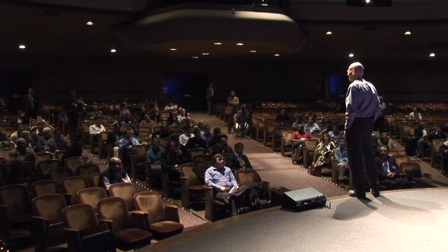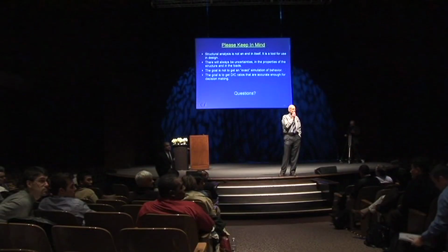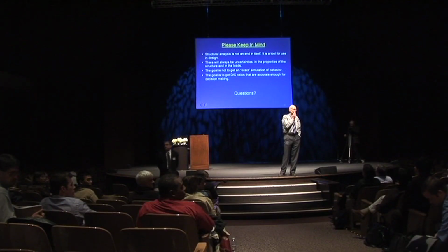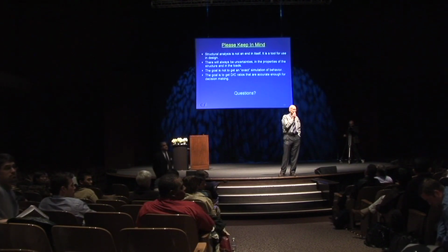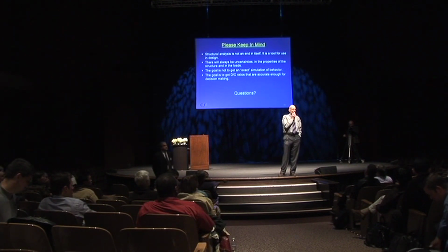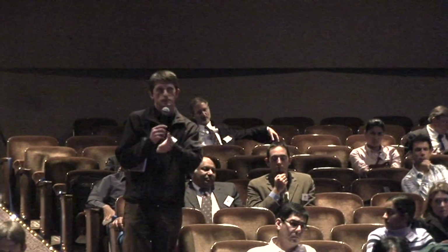Okay, and then another question regarding modal pushover analysis. In your earlier session, you talked about doing combinations. You can combine different pushover analyses to get results. For the modal pushover, you need to combine all the hinge rotations using either SRSS or CQC. Can you use the technique you were talking about earlier to do that for hinge rotations? Can you do the modal pushover where you do several pushover analyses for one?